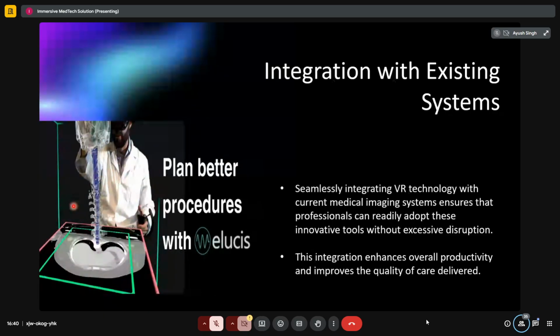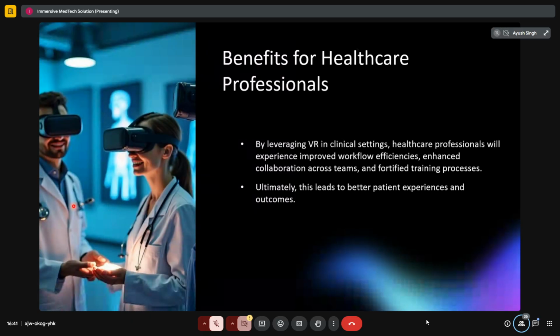If we are dealing with a hollow heart CT model, and for example the patient has a VSD defect and the surgeon needs to do pre-surgical planning for that, that too can be done in a very efficient way. We can directly bring in the CT data set, and once it has been brought in, we do a single click operation of segmentation. We will highlight that particular part, and once that is done, we will hollow out the structure if we are required to do the 3D printing of the same. I have certain test cases that I had earlier segmented and that were converted into 3D printed models, which I'll further showcase after this presentation part.